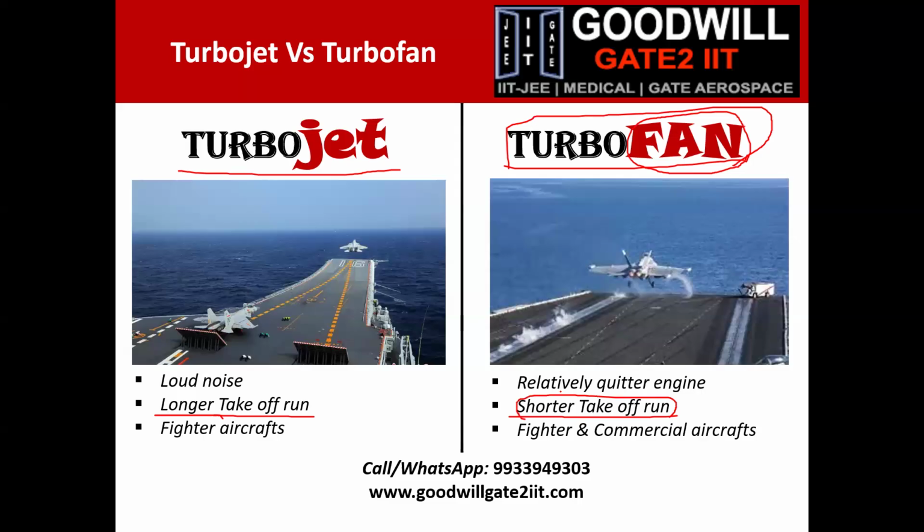Next advantage is they are relatively quieter engines compared to turbojet. And see the applications of turbojet: fighter aircraft, because they can travel fast, they can go to high altitudes. That's the major advantage, very lightweight. Whereas turbofan needs shorter takeoff runs, which is the reason it can be used for fighter as well as for commercial aircraft. They are better for low speeds as well.